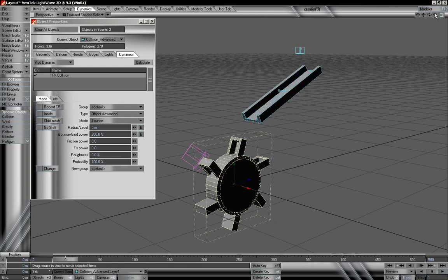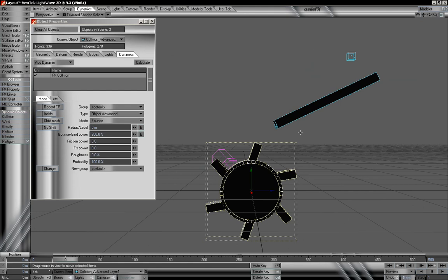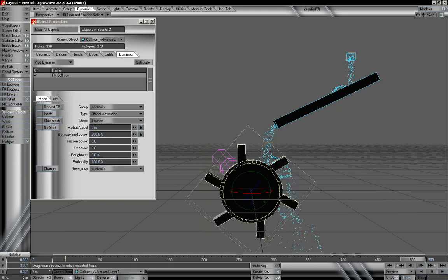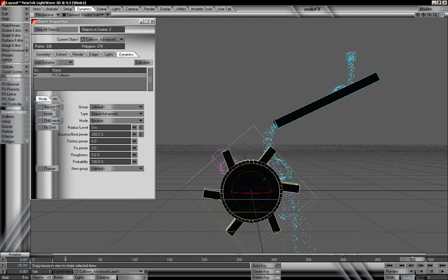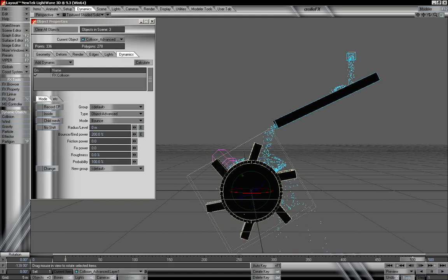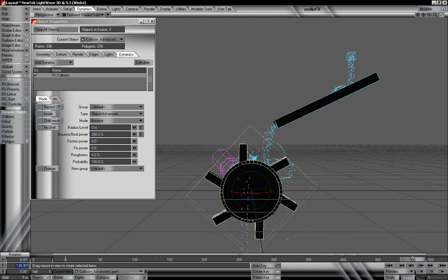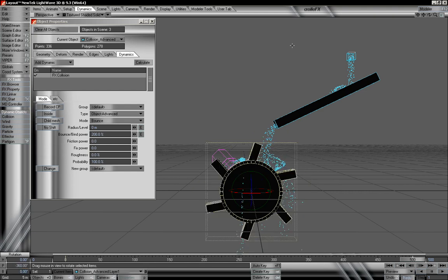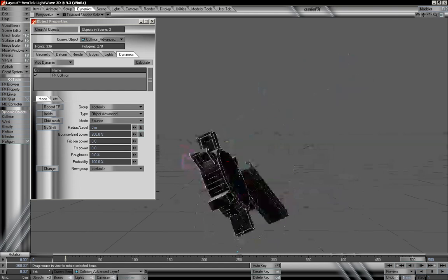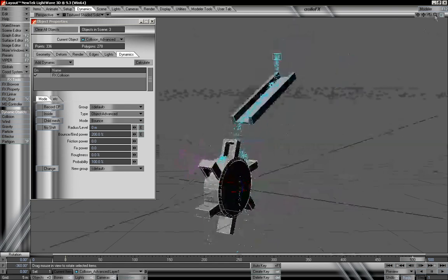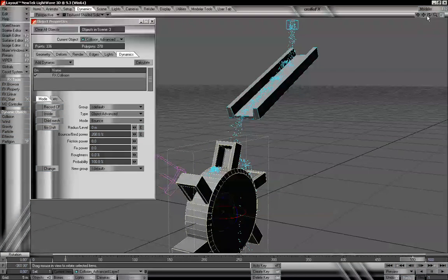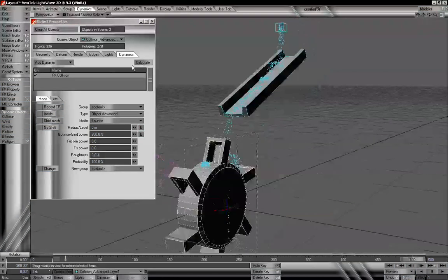And what I want to do is add some rotation to that object. We're going to go all the way to our last frame, frame 500, and switch to our rotation. I just want to increase our pitch on a negative amount. Let's go ahead and just set that to negative 360, which is going to give us one complete turn. We're going to zoom in a bit, and now we can calculate this effect.